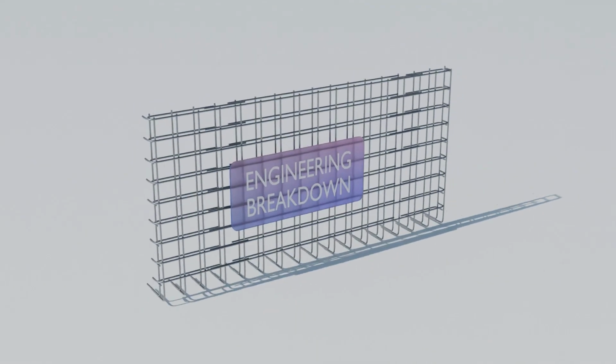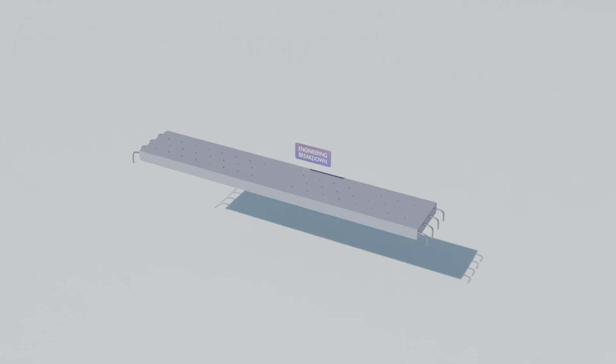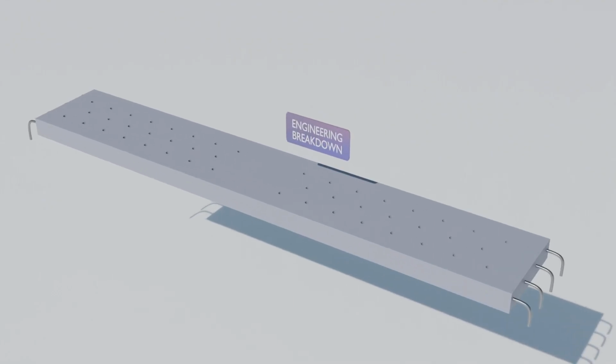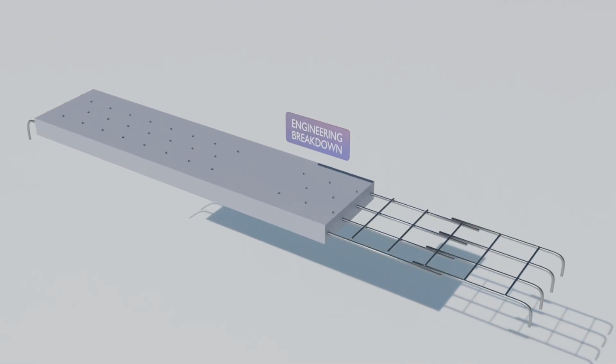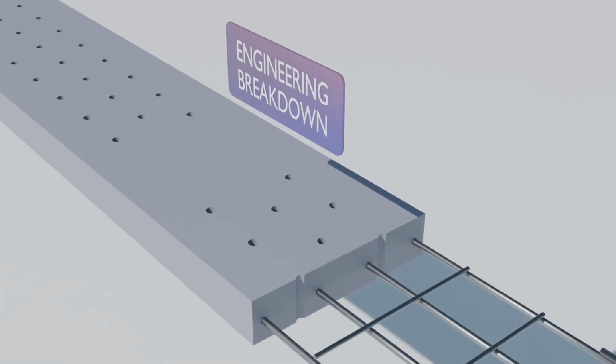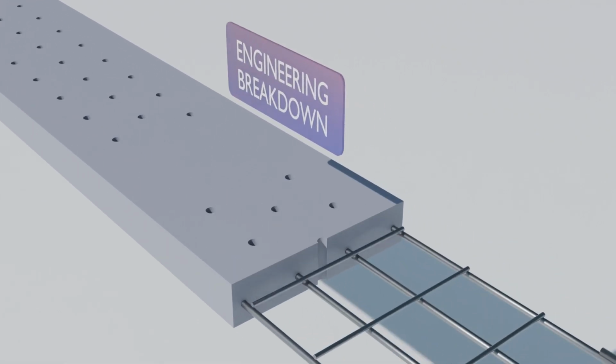Let's now take a look at perforated slab reinforcement. Perforated slab reinforcement should be provided in a way that it avoids the holes. As you can see, our bars avoid every hole in the slab in both directions. Let's look at it through the translucent material.